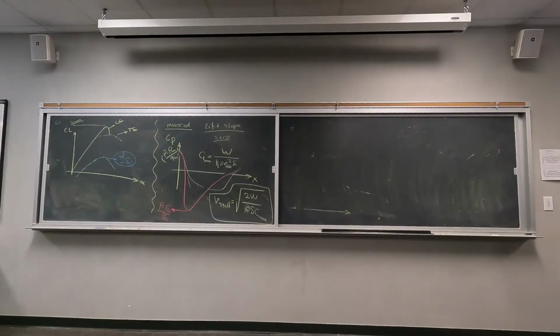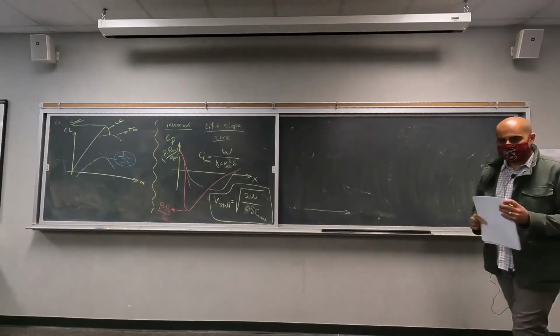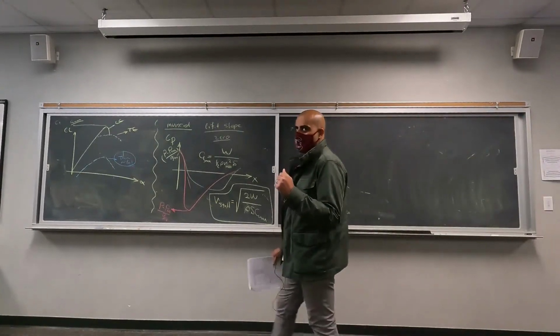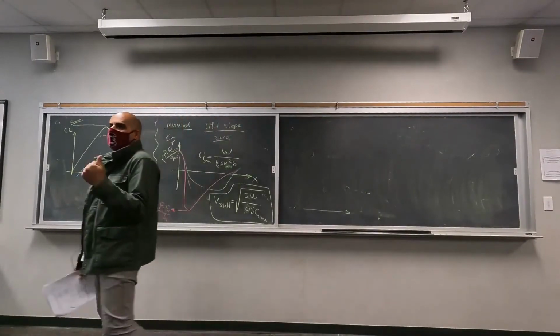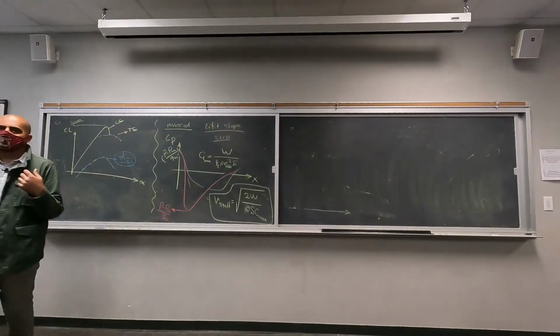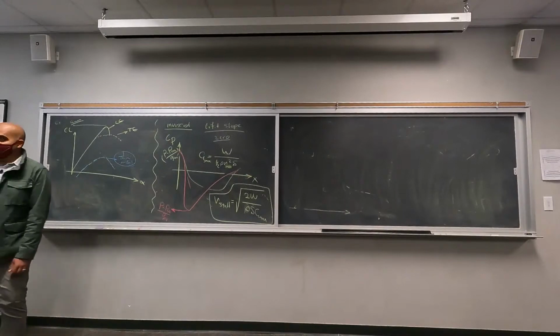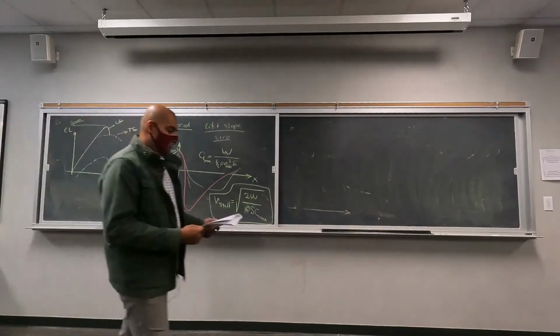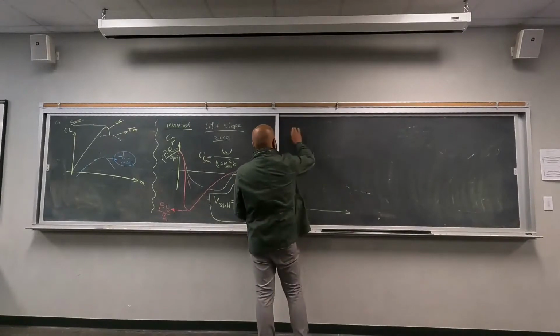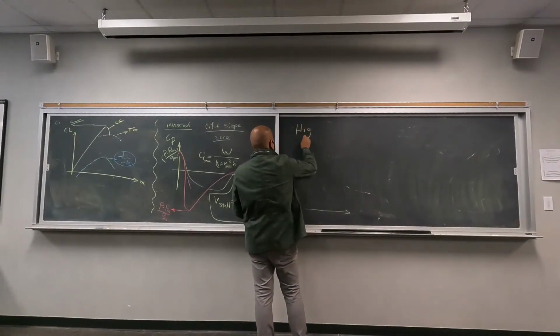We either want to come up with a mechanism that is going to help us delay the flow separation, okay? Or we want to increase the camber mid-flight. How can we do that? We have a couple, I don't remember who, but we have a couple of graduate students who are working on this as their project. Flaps and slats, right? Introducing flaps and slats, right? So flaps and slats are called the high lift devices.